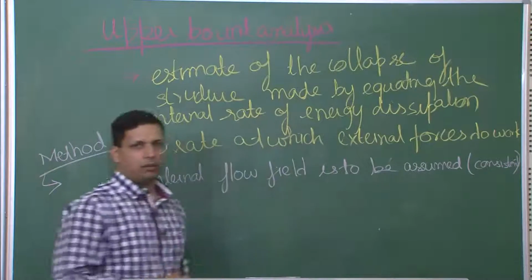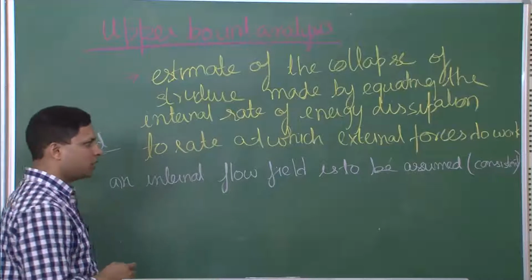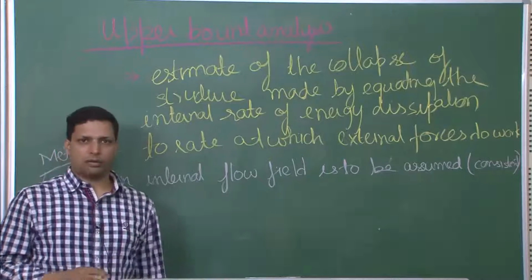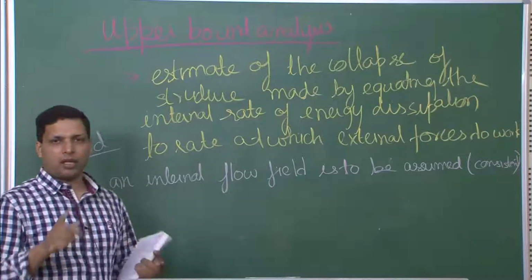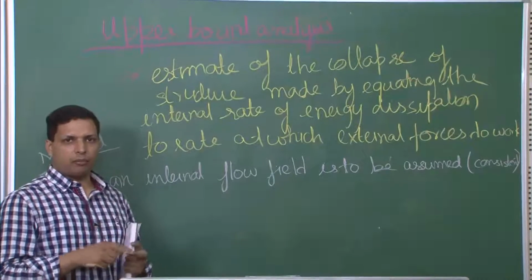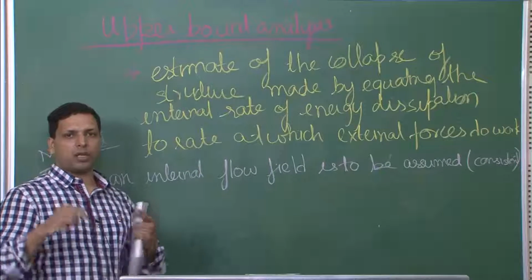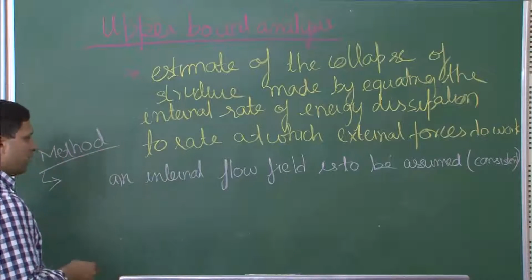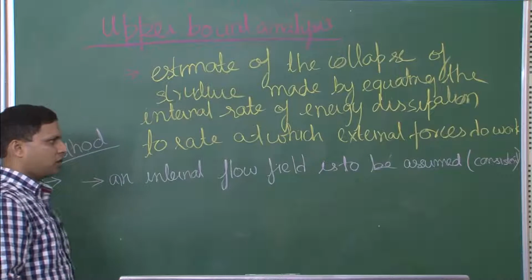And when we come to an example, I would show what exactly we mean by consistent. To put it in words, consistent means that you cannot assume that after deformation material is remaining inside the deformation zone. At some point the material, if it keeps moving after deformation, it must come out and so on. Some of these things when you put together, you can say these make it consistent behavior.